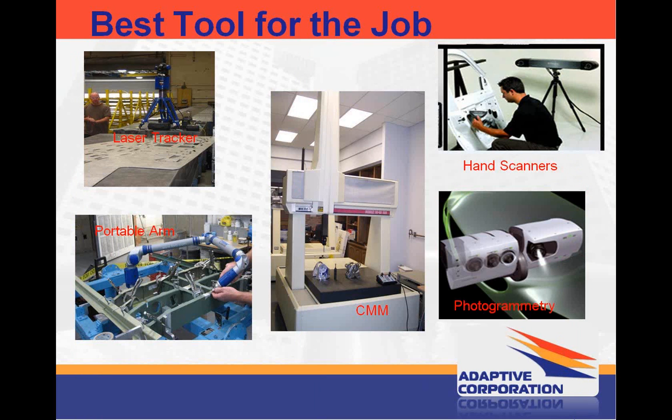There are a variety of options when it comes to scanning devices. The secret is understanding the task at hand, and then what do I want to do with the scanning results? Options include scanning a part to reproduce the math model of the part for manufacturing processes and downstream applications, scanning the part to create tooling, scanning the part for part validation or inspection. Does the physical part match the CAD data model? The answer you select to the above considerations may influence your approaches.